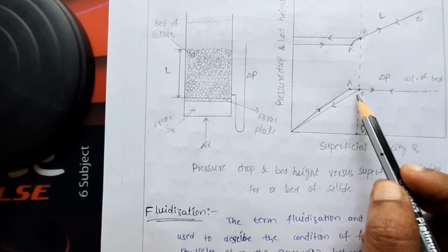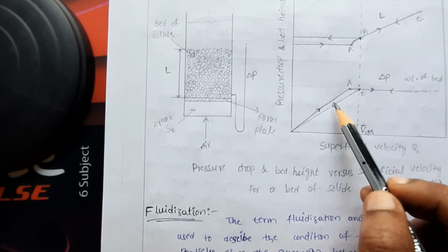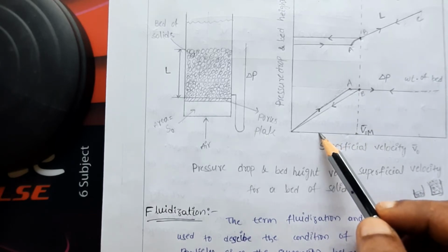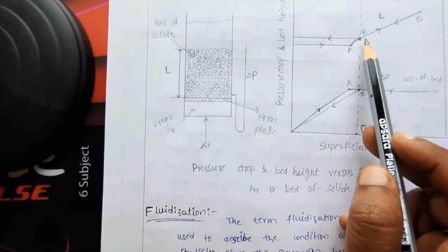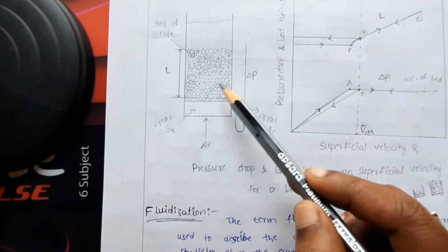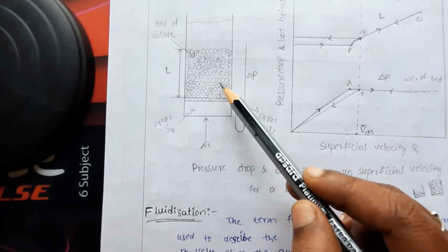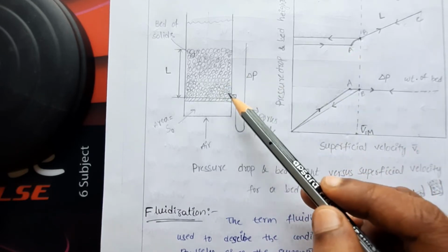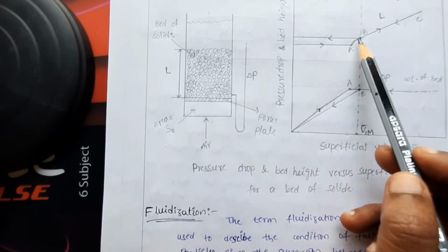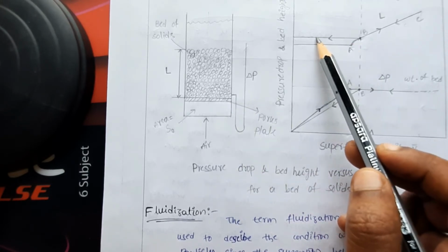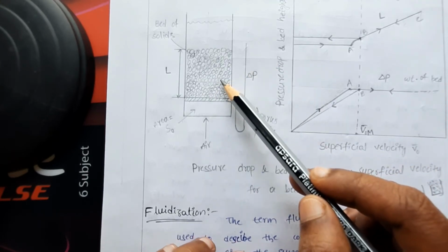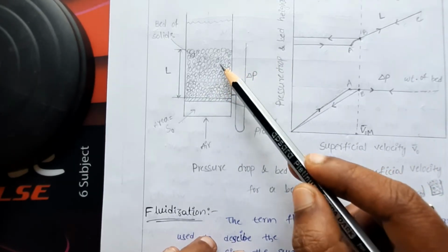It means the pressure drop in the fluidized bed condition will be less than in the fixed bed condition, if you decrease the velocity, whereas the bed height will be more than before, since previously the particles were dumped into the tube and tightly packed. Once it is fluidized, the tightness will be little bit decreased, since they are slowly settling down in the tube and that much tight packing will not be there, since they are little bit loosely packed in this case.